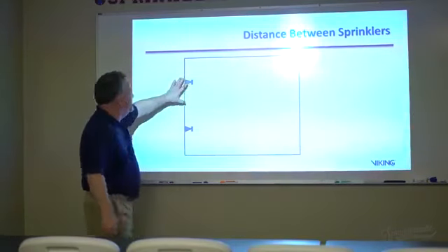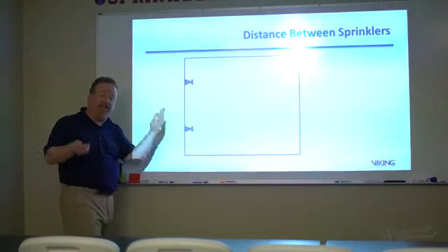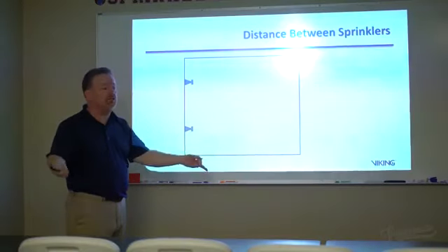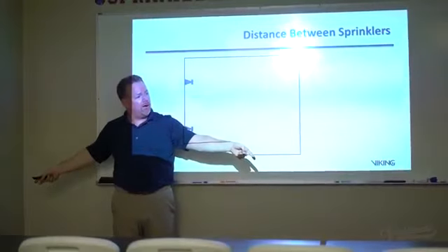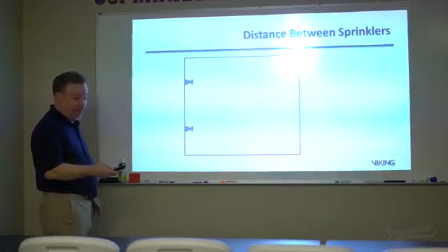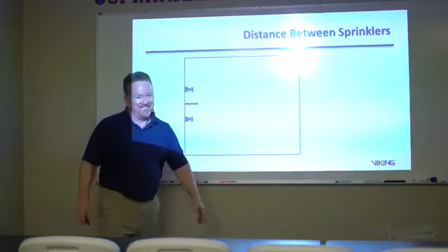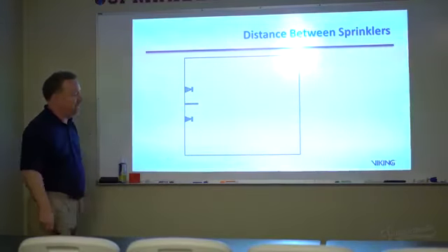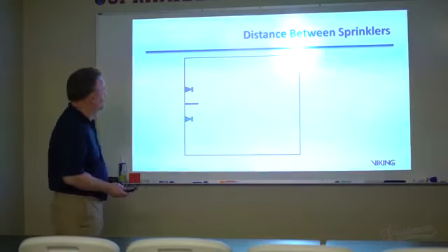Anyway, the distance of sprinklers to the wall is one thing, but then we get to the distance of the sprinklers between each other. Remember, the same thing happens if you get these too close. They are not just spraying out into the room; they're spraying down the wall. So if you get these too close, ready? Here it comes. Put a baffle between them when they get within that spacing. That woke everybody up. That's what you need, a little animation.